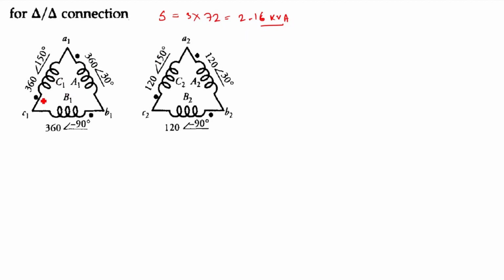And the winding arrangement, if we'll make, so all the phase windings will be connected in the delta fashion, we can see here, right? And for each of the windings they are connected in delta fashion. If we'll connect the voltage sources, now your voltage will have an angle of 30 degree, because this will be the leading voltage VAB1, right?